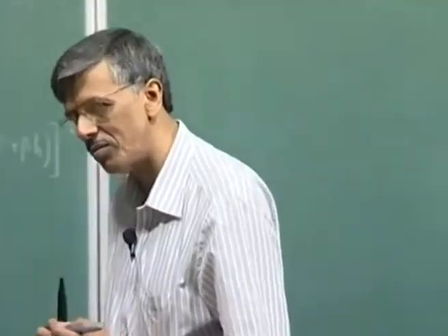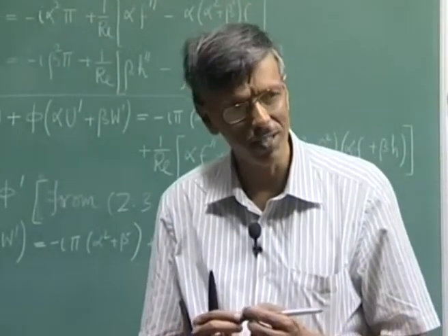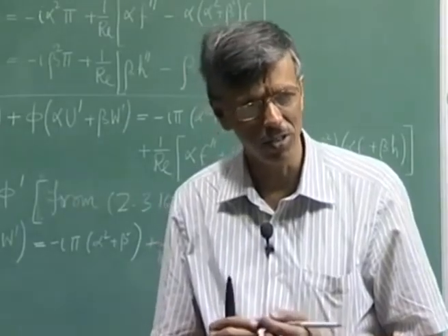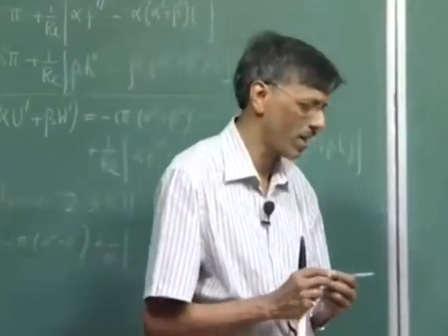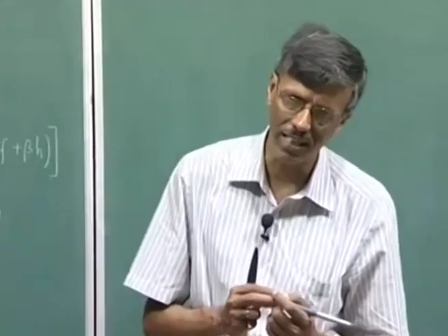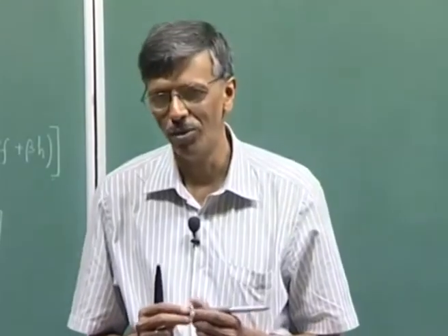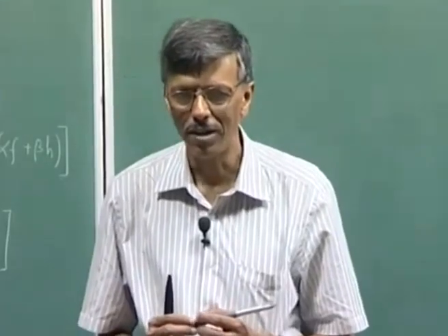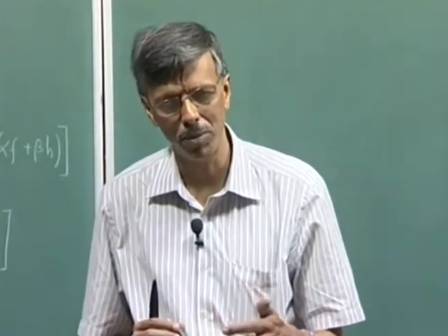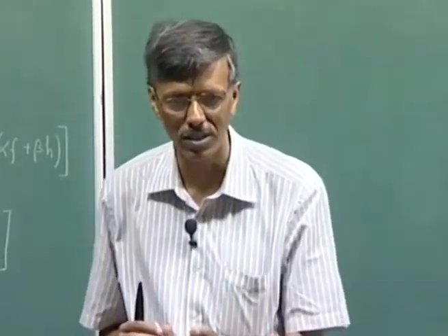This also brings to your mind what we talked about in terms of Kelvin-Helmholtz instability. There we found the disturbances were essentially 2D, right. The group velocity in the other direction was 0. So, what it basically tells you is that when it comes to stability studies, it is not necessary to make the problem more complex. Even the 2D flow will give you an early indication of whether the flow is stable or unstable. And if there is simultaneous presence of 2D and 3D disturbances, 2D disturbances are more catastrophic than 3D, right.